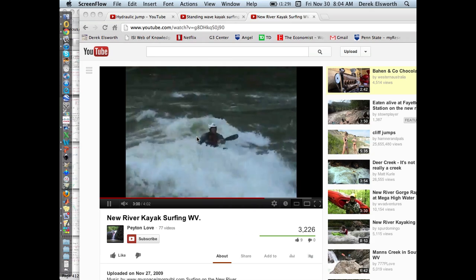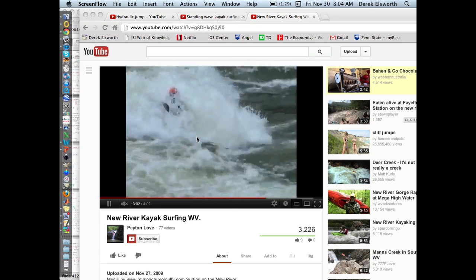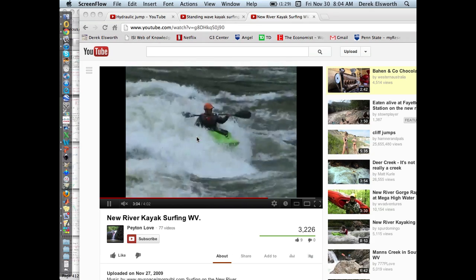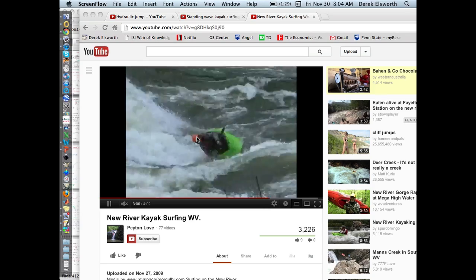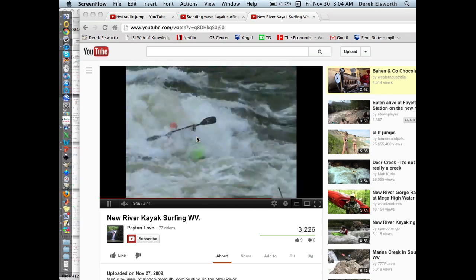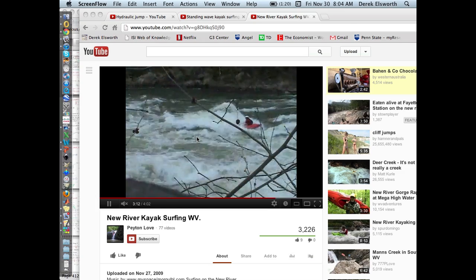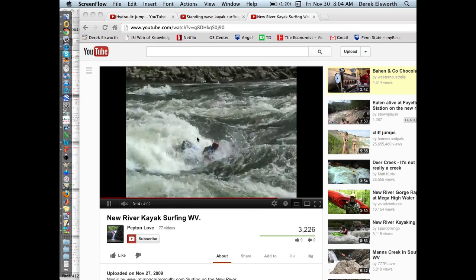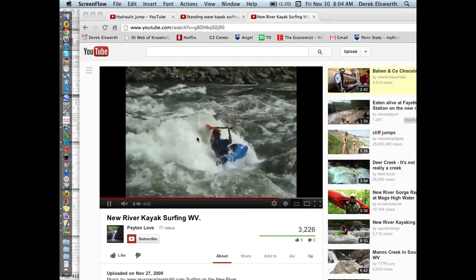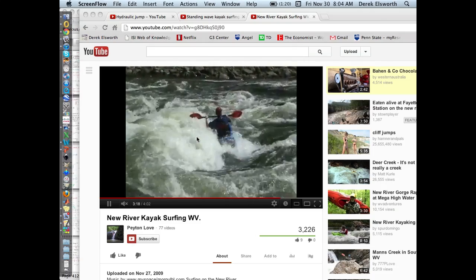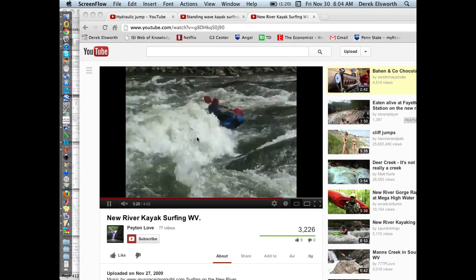So if you have flow in a pipe, it has to fill the section of the pipe, and it can't be any larger cross-sectional area than that, and so that's constrained. But if it's flowing in a channel, then you could imagine that it could either flow very quickly and be quite shallow, or flow much more slowly and be deeper, and still have the same volumetric flow rates.